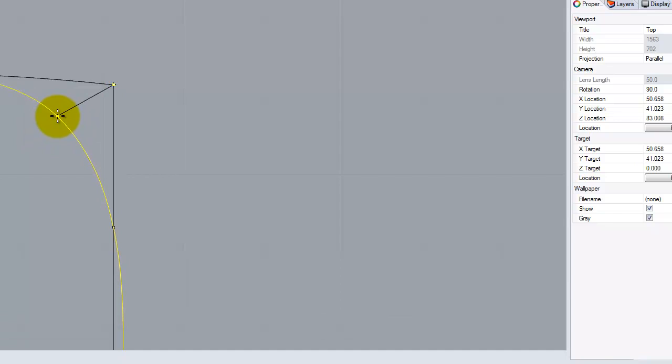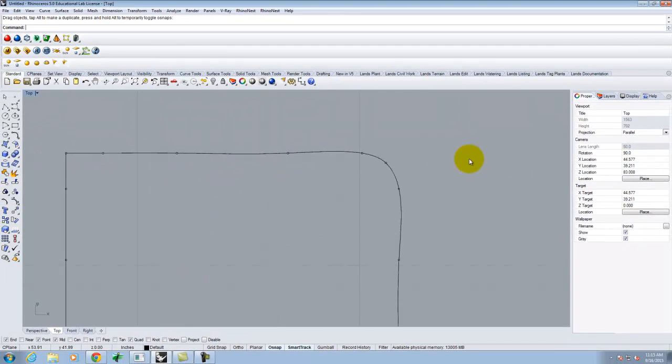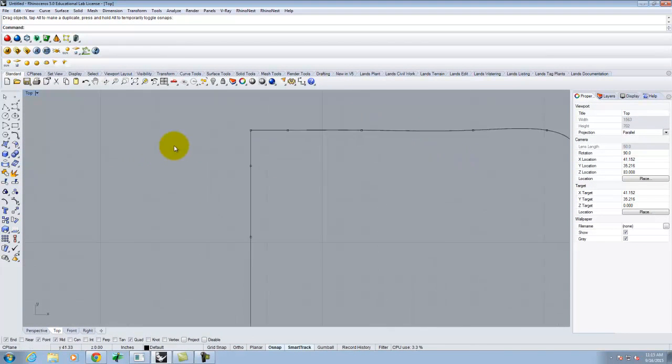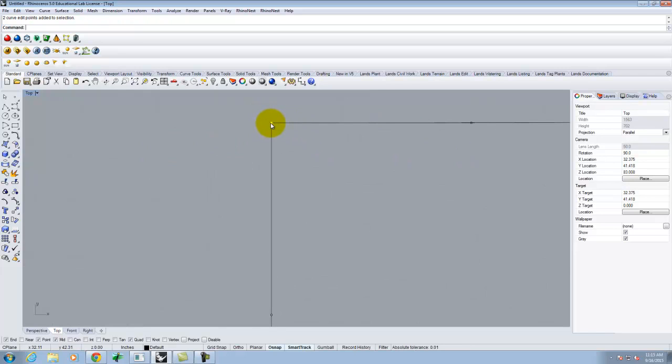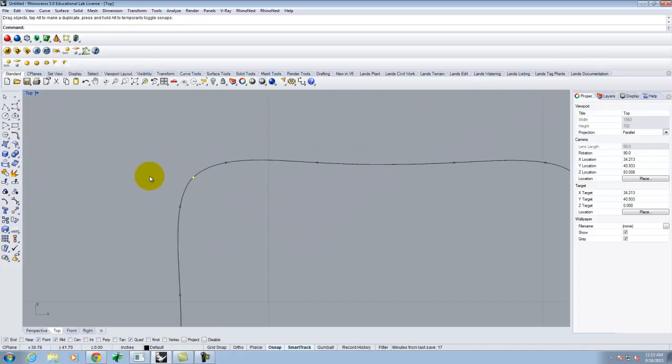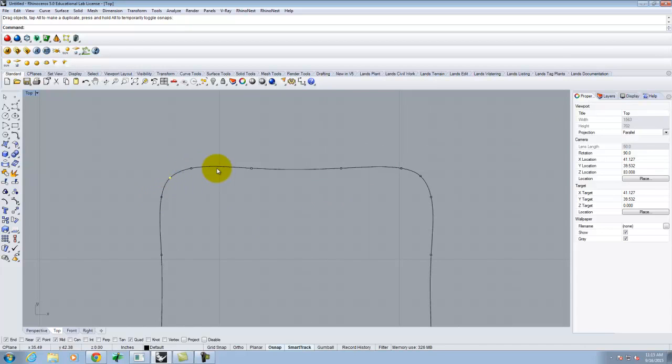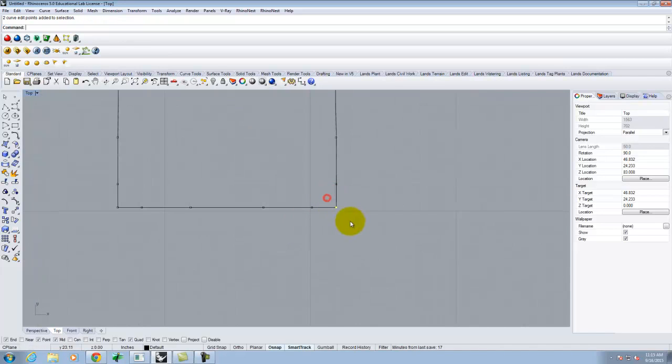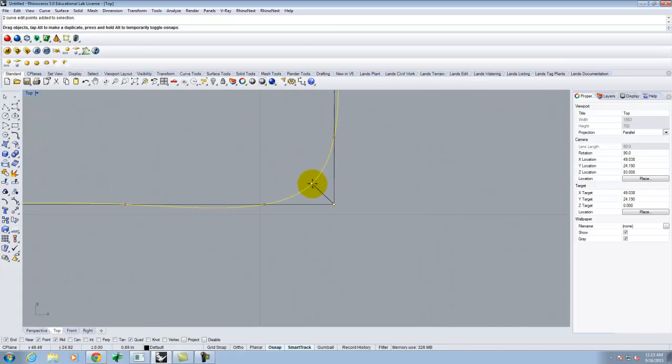All right, and if you judge by your eye, you can get to a point where they kind of round out very nicely. Okay, we'll do the same thing. If I didn't want this to impact the side of the cushion quite as much, see how my cushion went from being straight to now it has a little bit of a dip in it, right? I could rebuild these surfaces with more points, in which case I'd get less of a dip, right? The more points you have, the straighter it ends up being long term. So let me go ahead and move this in, right?